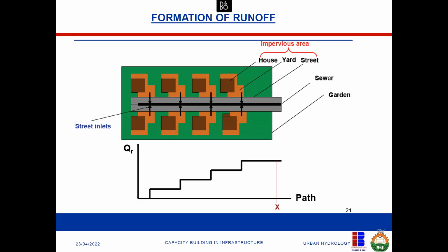Now, this is typical of how runoff forms. If I have my outlets here, and these are catchments or houses contributing to runoff, whether sewer or storm, in this case it's the same thing. The difference is that in the case of storm, this will be an open drain, or a big pipe of not less than 600 mm, between 600 mm and 1.2 meters.